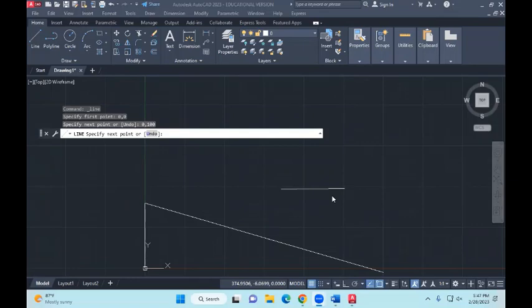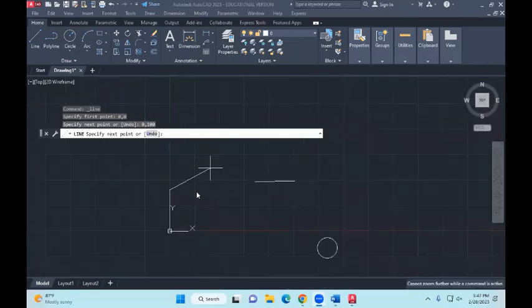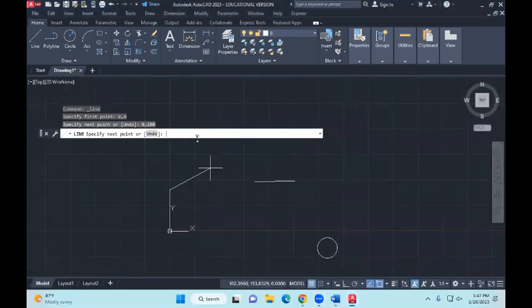So don't cancel out of the line command. You see, it's still active, right? If you move the mouse, the crosshair moves. So the third coordinate is 100, 100. Then you hit enter. So now you are more than halfway completed. You see what we are doing here? We are using coordinates to draw in AutoCAD.